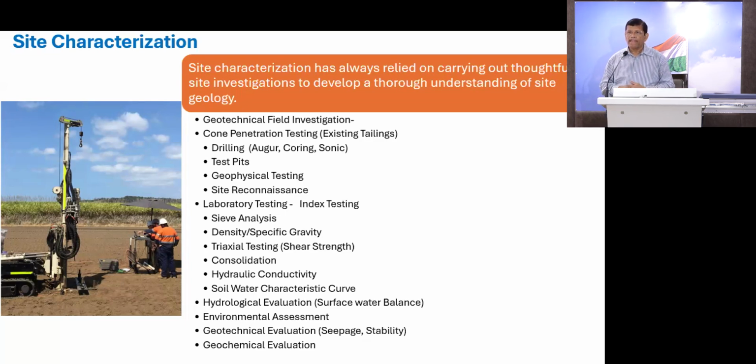So sir, is sonic continuous sampling or continuous testing? Yes, it is continuous sampling. Because in SPT we get a sample every 1.5 meters. Exactly. Here, for 5 centimeters, 10 centimeters, 15 centimeters, you continuously get samples. It is continuous sampling, like coring.